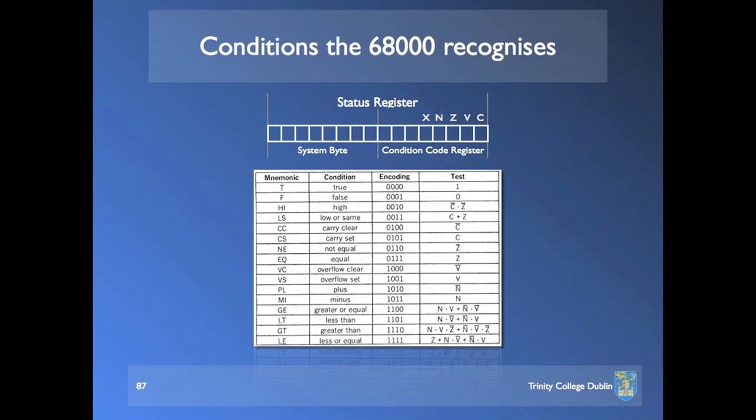And basically what you did was you took the least significant two digits and multiplied them together. You took the less significant digit in one case with the more significant digit in the other, 6 times 3, and you shifted them to the left by one digit position because one of the digits was already shifted to the left. And you did the same thing again. 6 times 4 is 24, shifted to the left by one digit position, and then 6 times 9 is 54, shifted to the left by two digit positions. So you got four partial results and you have to combine them. Okay, that's long multiplication.